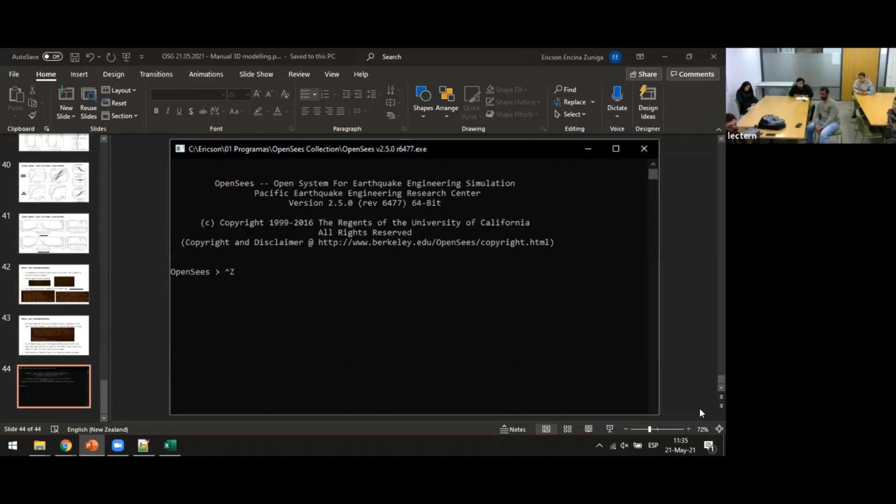But when I moved to the big building, all of those elements caused a lot of trouble. What I ended up doing was Concrete02 for fiber-based elements. I got rid of the zero length elements and used an approach from Oyen in 2006, who published his master's thesis. He finds an alpha factor that modifies G, the shear elastic modulus of concrete, so you can account for both the shear deformation and the strain penetration at the foundation interface. And that's what I ended up using.